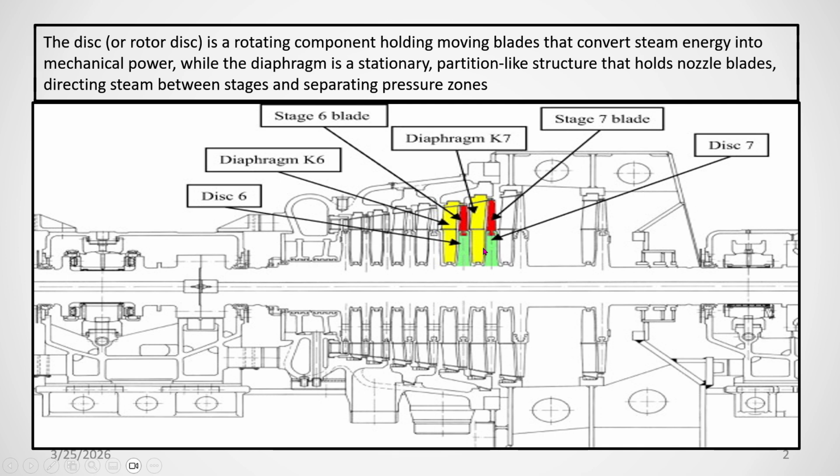These rotary blades are subject to high RPM, while stationary blades normally remain stationary. Steam will pass through here and change direction, a little pressure drop will take place, and the rotor blades are subject to high centrifugal force.